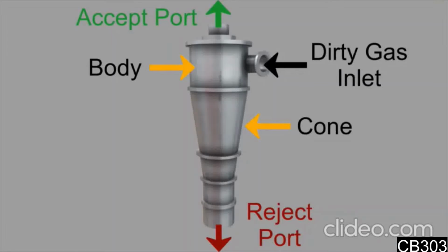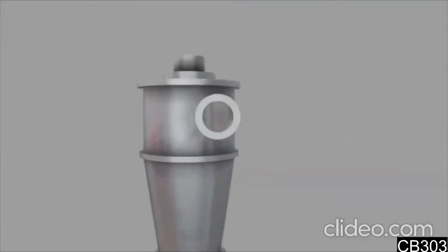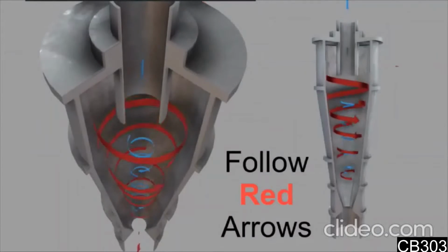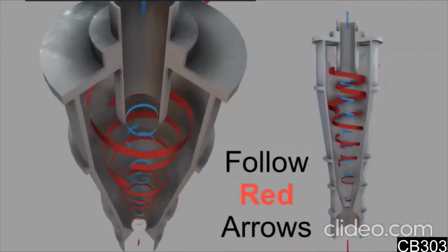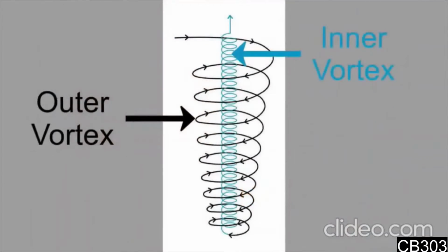Now we talk about the working of the cyclone separator. Gas containing dust particles enters at high velocity through the tangential inlet at the top of the cyclone. The gas flows into the cyclone body tangentially and begins to flow in a circular downward spiral toward the lower reject port. This downward flowing spiral is referred to as a spiral vortex. The cyclone diameter gradually decreases, which causes the gas velocity to increase. The outer vortex creates an additional inner vortex closer to the center of the separator body. This inner vortex flows in a spiral upward toward the accept port.